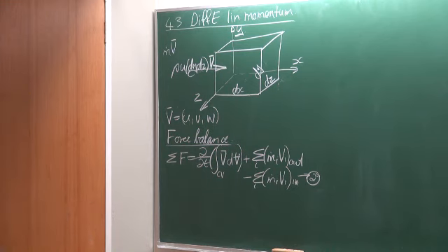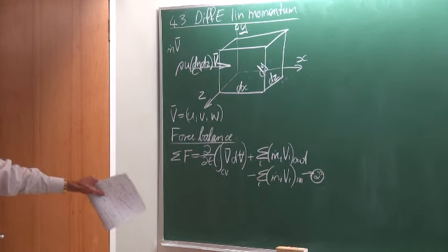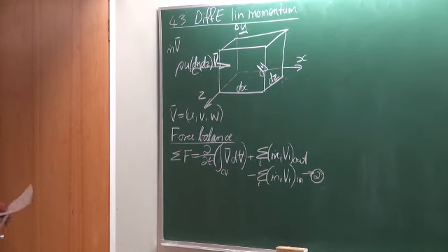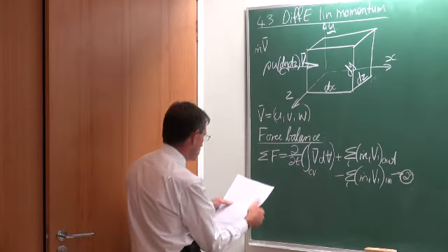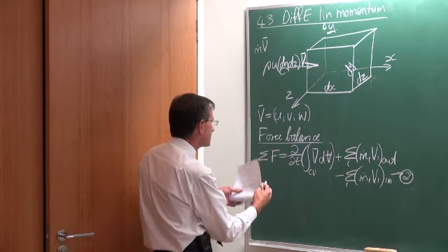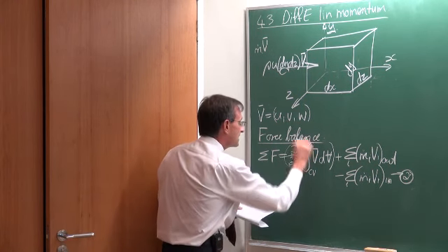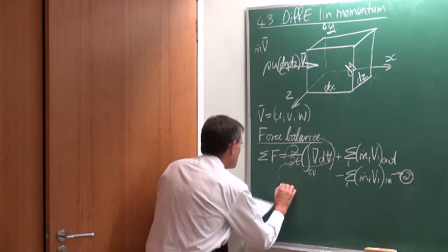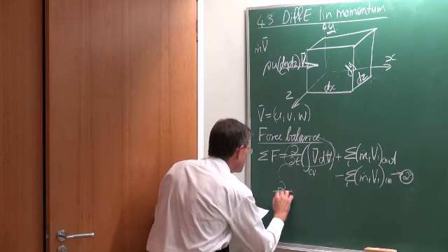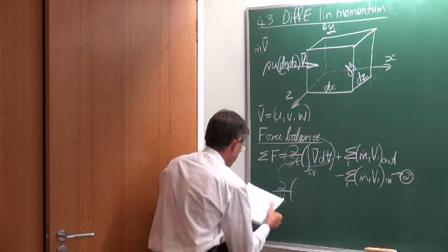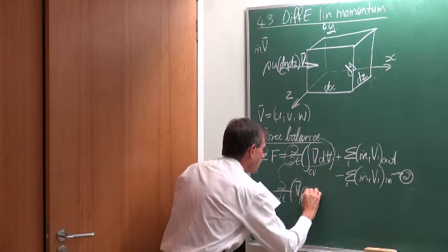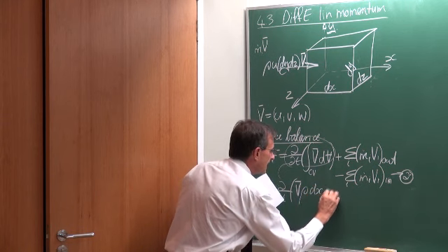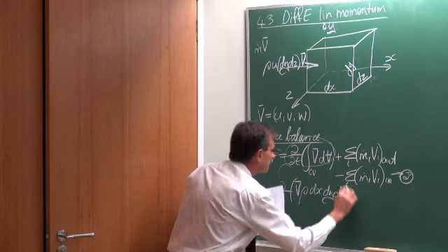Okay, so that would be equation 2, and equation 1 from the previous lecture is the continuity equation. Again, because it's a small element, we can say this term is equal to partial d/dt of the velocity vector multiplied by rho and dx, dy, dz.